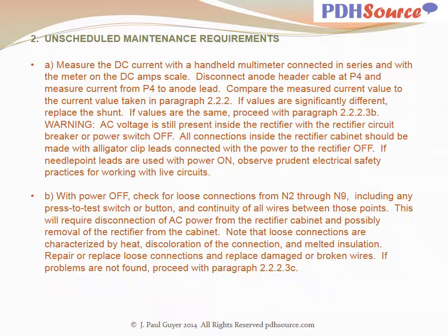A word of warning: AC voltage is still present inside the rectifier with the rectifier circuit breaker or power switch off. All connections inside the rectifier cabinet should be made with alligator clip leads connected with the power to the rectifier off. If needlepoint leads are used with power on, observe prudent electrical safety practices for working with live circuits.